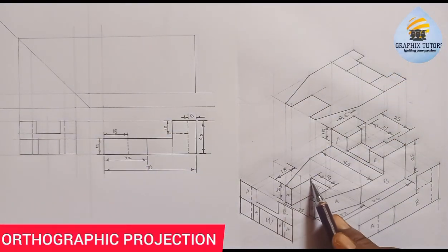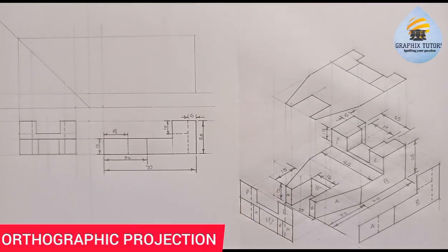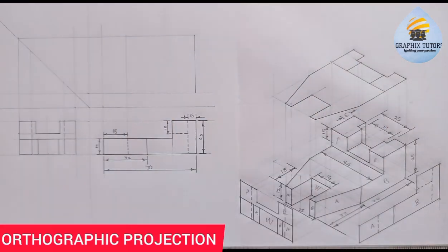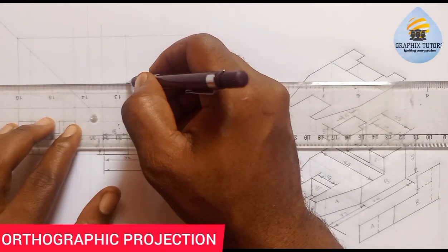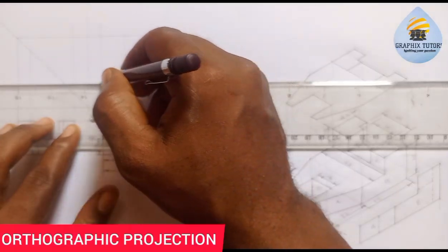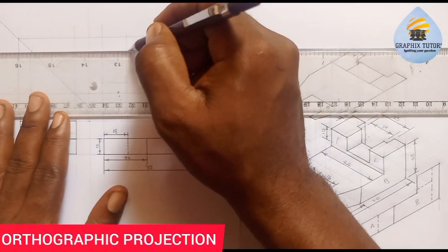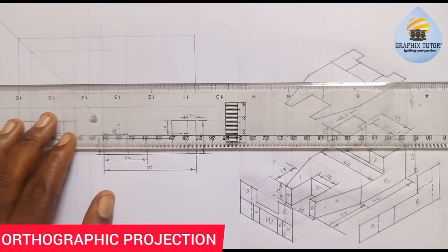Because when you are dealing with these 2 points here, it goes in by how many? 16. And the 16 is this hidden line you're seeing here. So if I should project this here, it means that is where they must not pass. So if I come here, I'll just place it this way, draw faint line, come here also, draw another faint line this way, right? They call this the imaginary line.